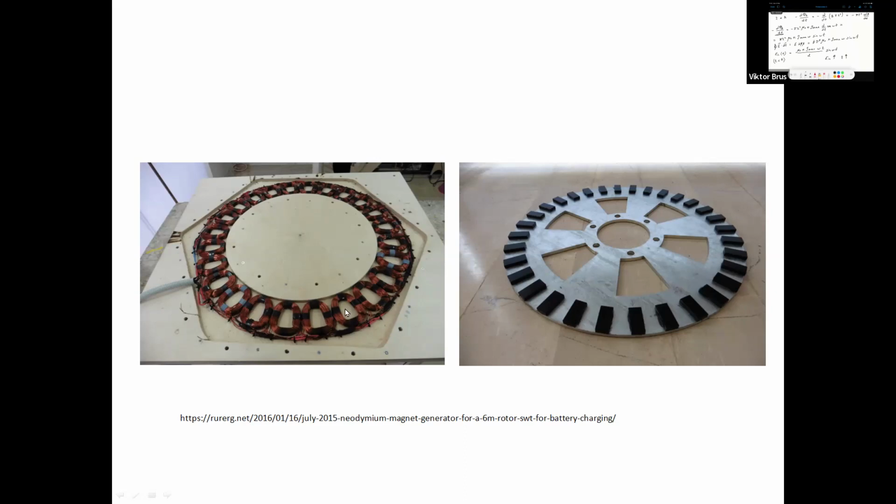There will be a change of magnetic flux through these coils of copper wire because of the moving permanent magnets. The faster this rotation happens, the higher the induced electric current and electromotive force collected at the terminals of all these coils connected between each other.